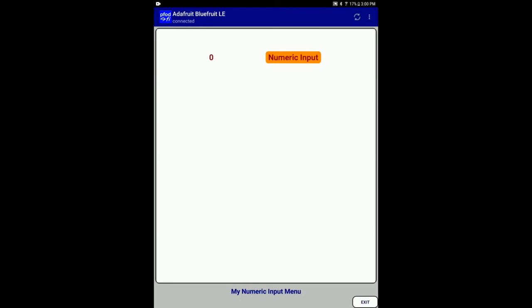For this example, it's going to be a numeric input. Just like 11A, where I had this input labeled string input, this one here I've just labeled numeric input. I'm going to click on it because I've got a touch zone set up there. You can see this little message near the bottom of the screen: enter value, max 8 digits, no decimal point numbers, use a check mark after entry.